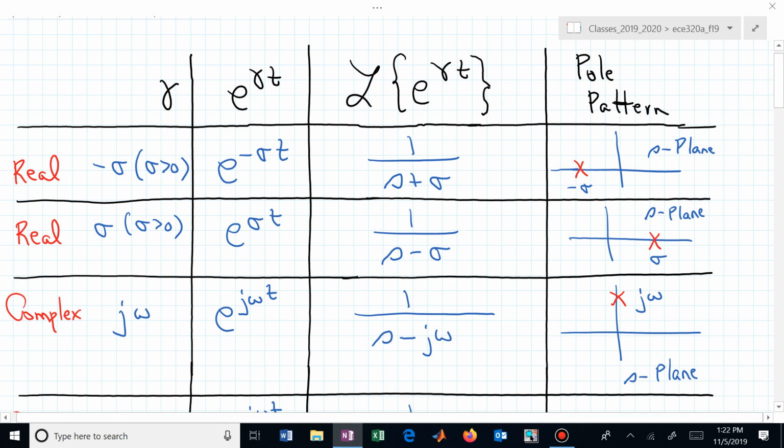So these transform expressions could represent a signal in the time domain. They could represent a system in the time domain, and you can combine them. You can multiply in the frequency domain. That's the beauty of the Laplace transform. The transfer function of the system times its input's Laplace transform, capital X of s, generates the output in the frequency domain. If you need it in the time domain, it'll be little y of t. Anyway,